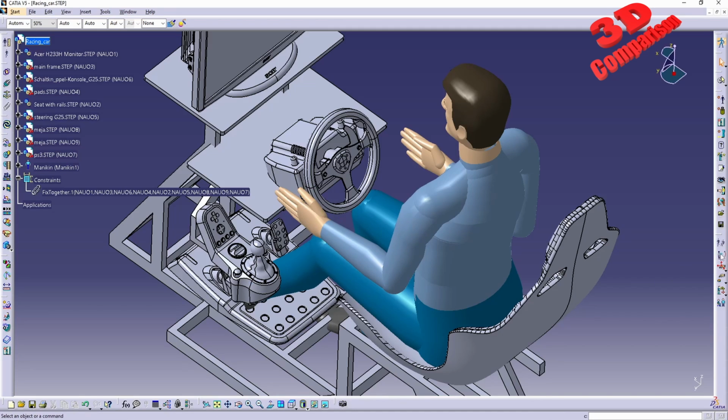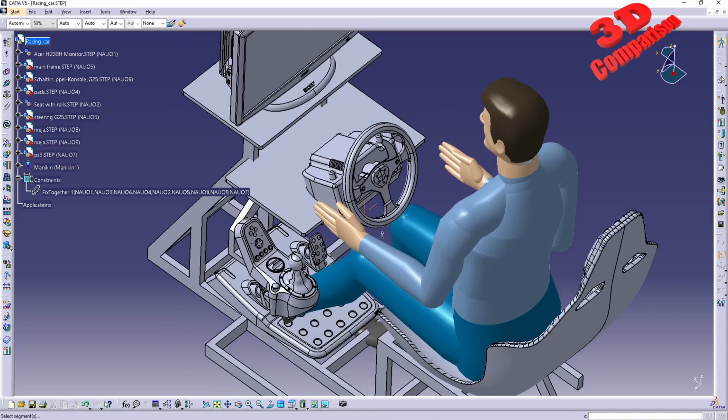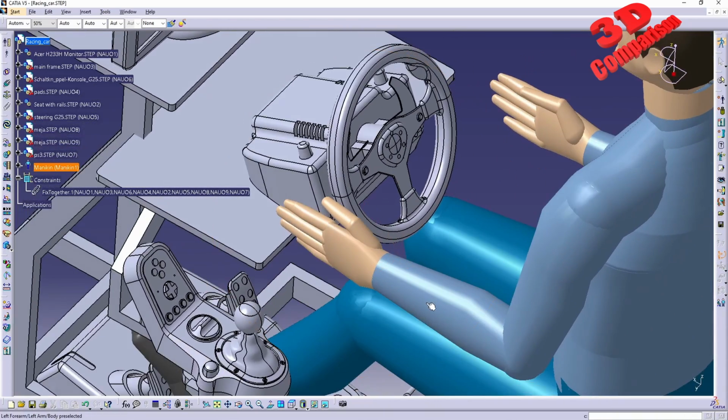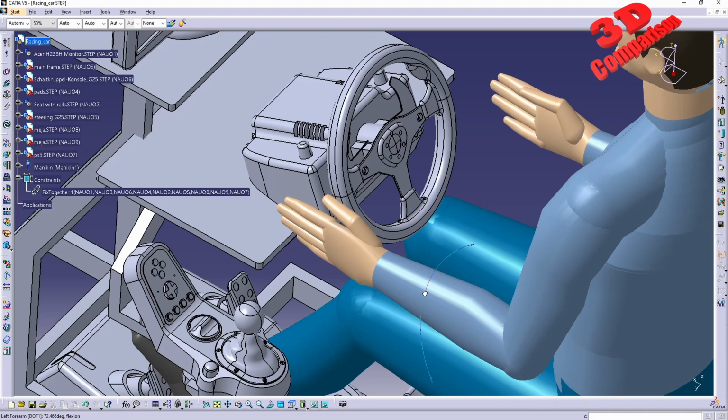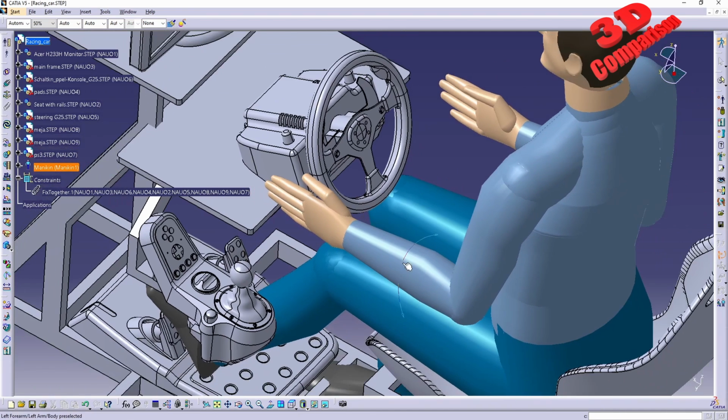And we can also make use of the forward kinematic. I can select, for example, this segment, and I can move it up and down. And if I want to change a different degree of freedom for this one, I can just right click and I will obtain the other one, in this case degree of freedom 3, which will be this axis. So I can twist the hand like this.